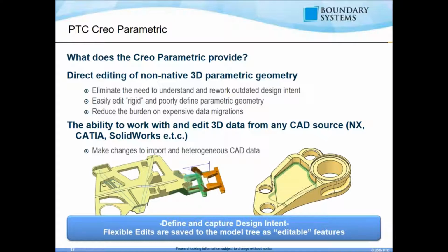And in the case where it's a geometric design change, then Creo will essentially warn you and say, hey, we need to convert this, and it's just a simple one-click button at the time to convert from CATIA or NX to Creo, and you can go ahead and continue making your geometric design changes, right? So this essentially enables that you can leverage existing CAD data, right?